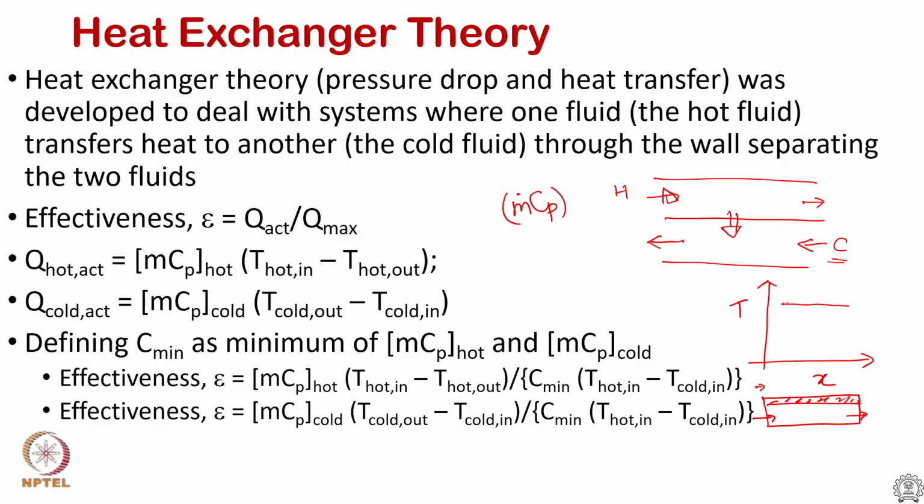However, the temperature of the air that is incoming, it is going to start at a lower temperature, that is the ambient temperature, and keep rising in temperature. Eventually, it may reach the temperature of the metal, and this is your fluid. This fluid may attain the temperature of the solid fin if sufficient length was provided to it. So what this is saying is that now my solid temperature can be treated as if it has a capacitance that is much larger compared to the fluid side.